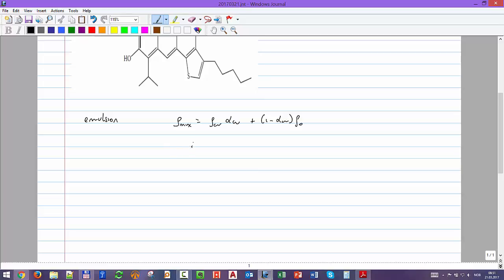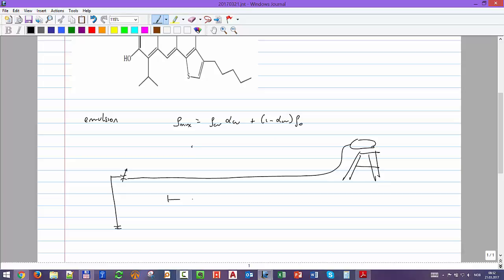Well, what I was saying is, let's see, we have our well. Now we go to, again, the boring part of the teaching. Let's say that's a very long transportation distance, 20 kilometers. People say, why transport the water all the way from the well to the facilities if we can just put a certain component that will separate and take out the water? And the people promoting that technology say, we don't like this mixing, because that creates a very stable emulsion, and then when I come here it's very difficult to separate. So let's just remove that choke, and to control production, they say I can still put a choke someplace here.